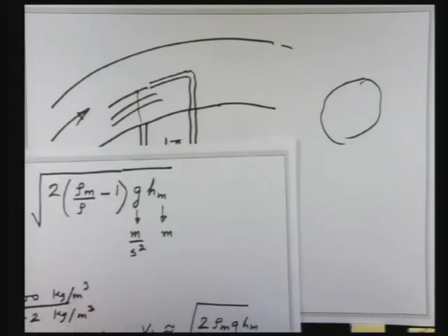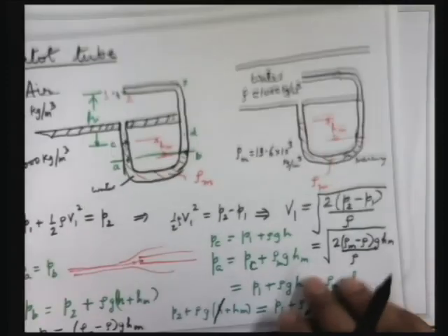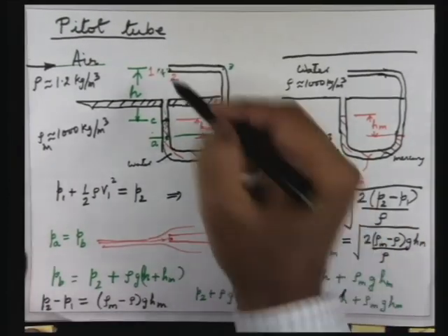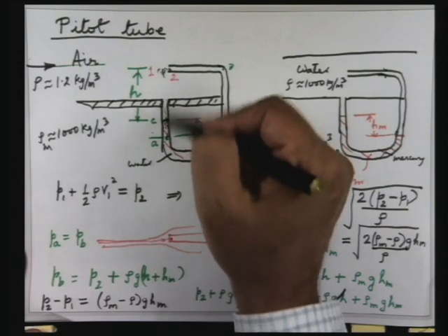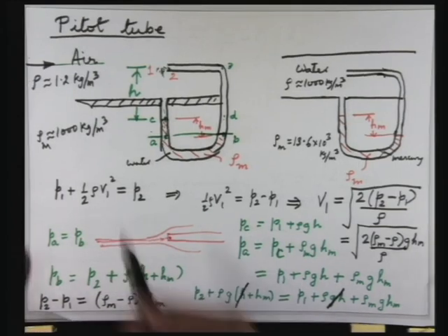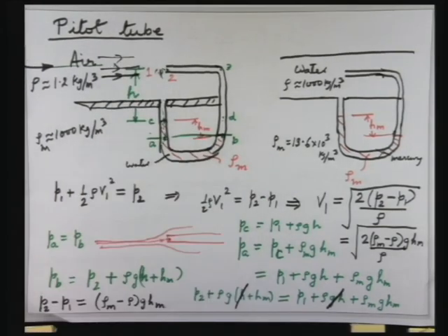So nobody asked me any question when I looked at this case, which is not a fluid at rest, and to find the pressure at this point, I simply used the hydrostatic relation. This hydrostatic relation can be used here because the streamlines are straight lines, which means the radius of curvature is infinity.